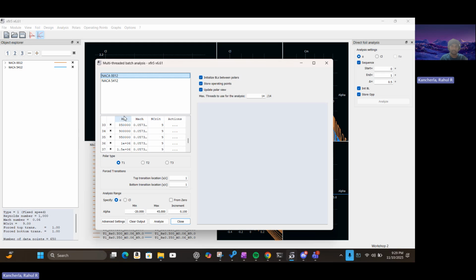These two can change to whatever you want, but these Reynolds numbers have to be the exact ones that I have, from the first one all the way to the 44th one. It has to be these numbers, or to my knowledge, the analyses do not work.